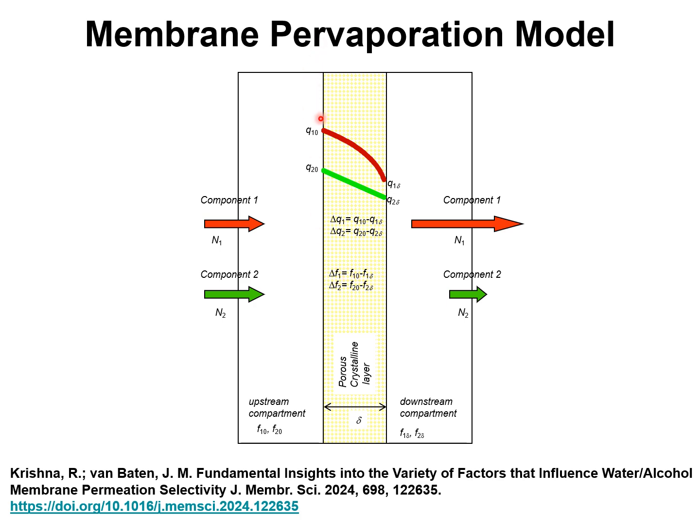The upstream face of the membrane is in equilibrium with the bulk phase mixture, and the component loadings for water and ethanol can be determined using the real adsorbed solution theory. The adsorbed phase mixture diffuses across the membrane, and for description of the mixture diffusion within the microporous crystalline layer, we use the Maxwell-Stefan formulation, taking due account of thermodynamic coupling effects as described in detail in my Journal of Membrane Science paper.